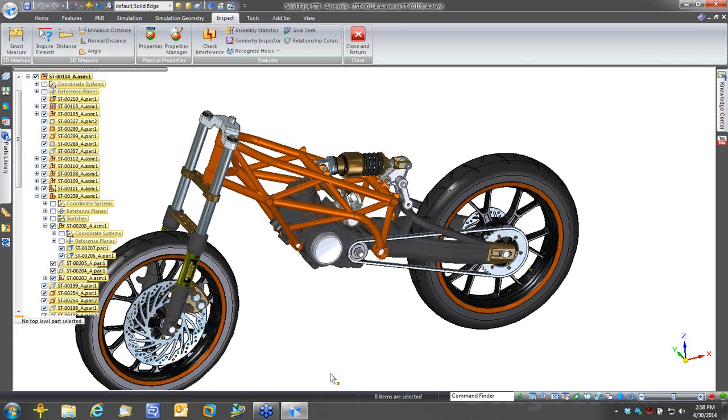I think direct editing is a little bit different than feature recognition. Direct editing doesn't actually build intelligence into the model. What it does is it just makes changes to the boundary of the model. So there are tools like move face, for example, but the end result is it's still a dumb solid with no intelligent features.